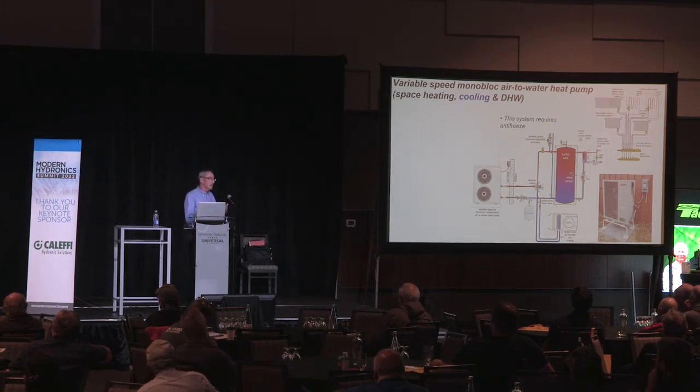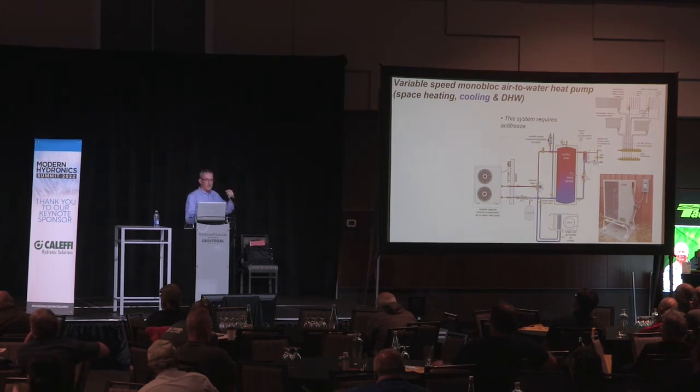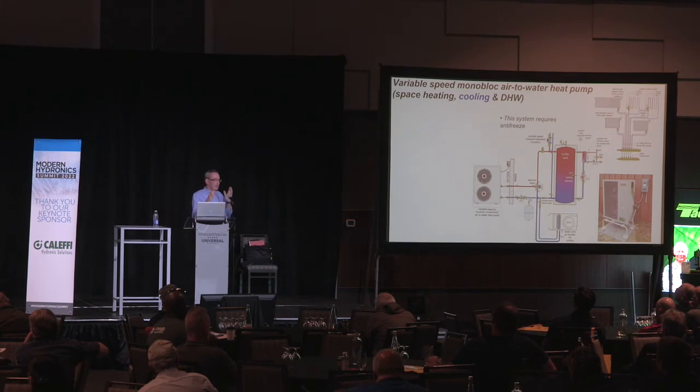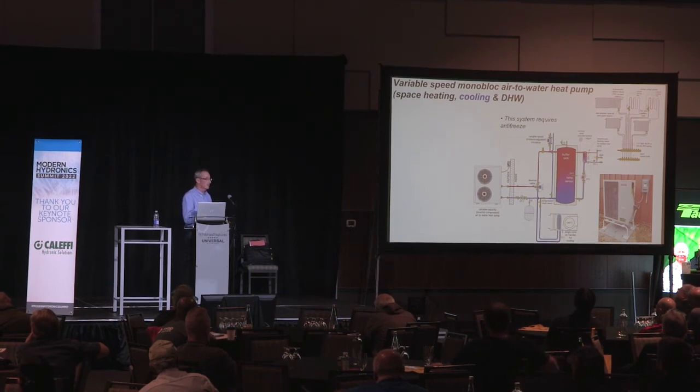When you size that heat exchanger, be generous. The guideline that I would suggest to you, you want the heat exchanger sized so that the difference between the incoming water temperature from the buffer tank and the leaving water temperature, which would be your domestic hot water now, leaving the heat exchanger, is no more than 5 degrees Fahrenheit. We call that the approach temperature difference on a heat exchanger. And even narrower is better, but the size of the heat exchanger will get large.